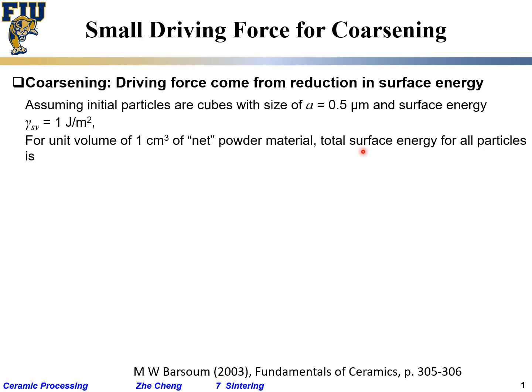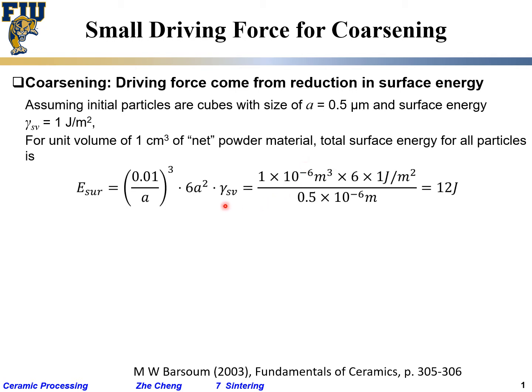And our total volume of the powder is 1 cubic centimeter, like your fingertip, something like that, that size, but all of them are powders. What shape of powder? Cube. And the same size, 0.5 micron. The total surface energy can be calculated. You just add it up or times it. I'm showing something like this.